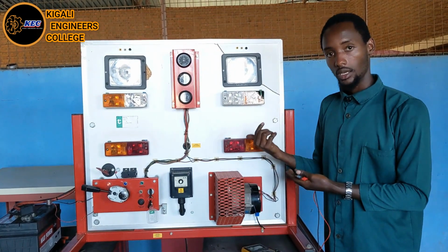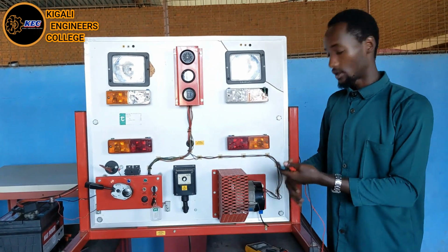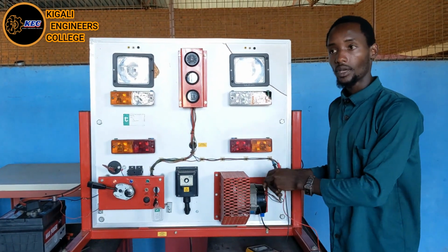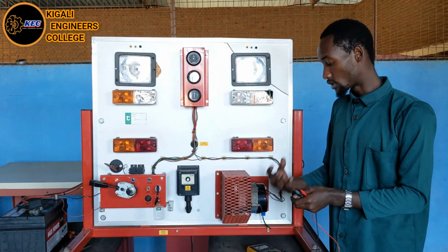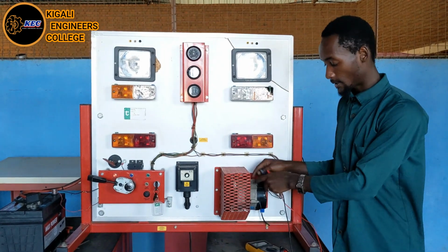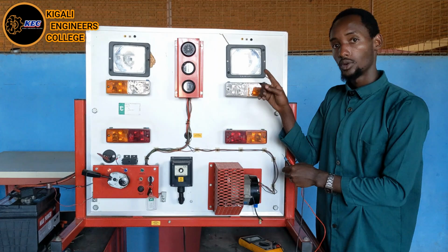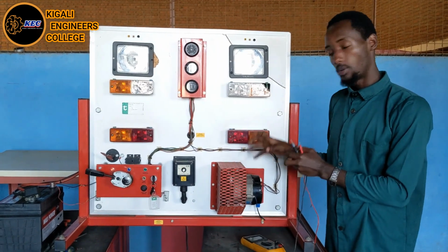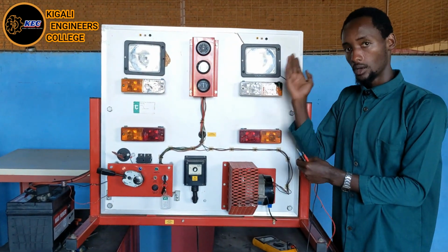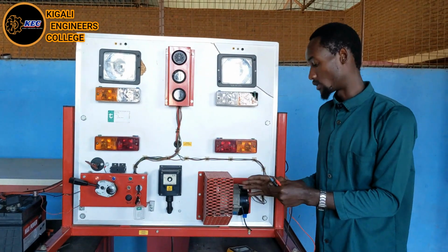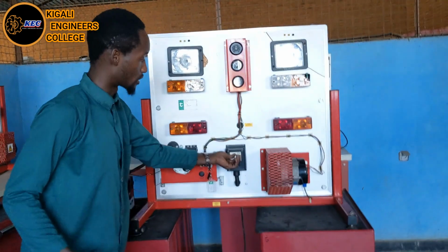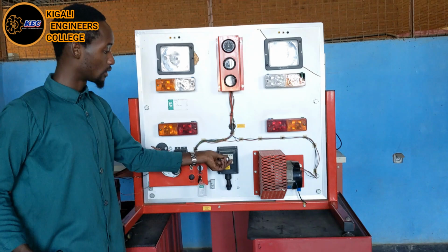If we rotate the rotor, that magnetic flux to the stator of this alternator will cause the induction of AC voltage passing through the winding of the alternator stator, as we showed you in the diagram, then through the power diode, and out of the power diode it will come out as DC current. So we are just going to turn our alternator on.